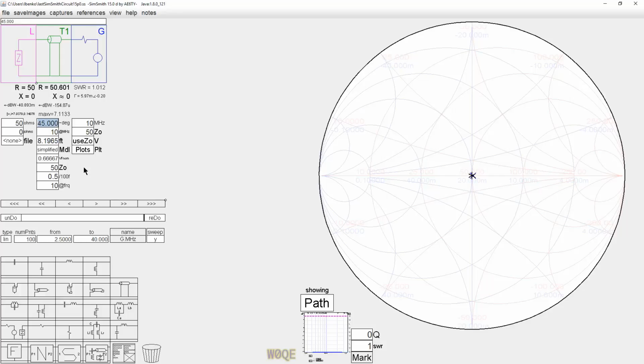Typically the gist of the argument is, if you have an antenna that produces an impedance around the 100 ohm range, and you take a 75 ohm piece of coax and make it a quarter wavelength long, you end up with something near 50 ohms. And we can demonstrate that, with absolutely lossless coax for the moment. I keep saying coax, but it's transmission line. It could be open wire, window line, ribbon line, anything you want. We start here at, say, somewhere around 100 ohms, and we make this 90 degrees long.